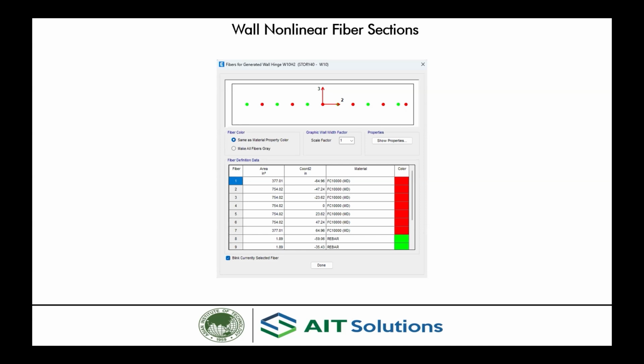And again, this saves us the time to calculate the fiber sections by ourselves. So if you go ahead and use these options, then we are saving a lot of time. ETABS actually offers a lot of features for the users so they can quickly come up with a nonlinear mathematical model by using these automatic hinges.